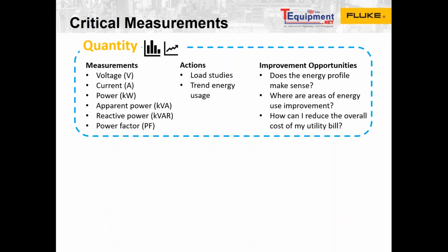When you're doing this, you may look for improvements in your overall energy profile. So that's like figuring out the pattern of your energy usage. So if you see something, for example, you know your facility is closed down on the weekend, Saturday and Sunday. If you have a nice calendar view of your energy usage and you see that you have a steady power usage Saturday and Sunday, then you know that you can shut maybe or lower the AC or heat, right? Or some machine is on that doesn't need to be on.